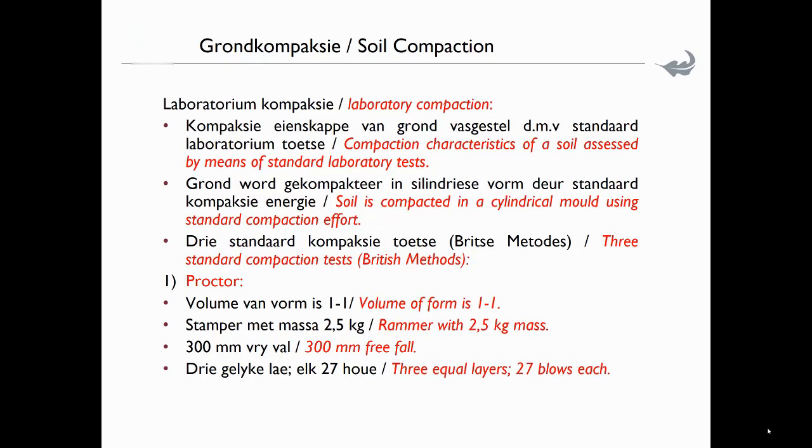In the laboratory, we perform different compaction tests in order to determine the characteristics of a soil, and we are using standard laboratory tests. The soil is compacted in a cylindrical mold using standard compaction effort. So this is the big thing. You need to be able to repeat the test several times and get the same answer.